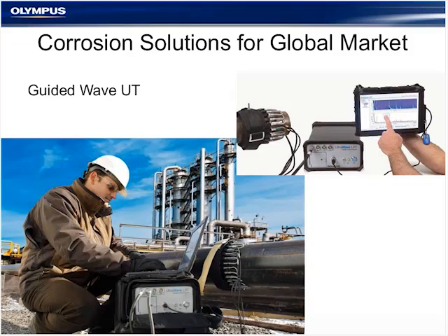It will also allow you to ignore any sort of coatings or buried pipes. So if the pipe is buried, it will give you a rough screening of how much corrosion might be present and how far down the length of the pipe. Now, is the tool perfect? No, it's not going to provide the same level of information as if you had gone utilizing an ultrasonic point thickness measurement or a C-scan instrument to do an area of pipe. But it allows you to get a pretty good indication if there's any massive corrosion along the length of the pipe and whether or not it's necessary to investigate further with either a point measurement system or something more sophisticated.